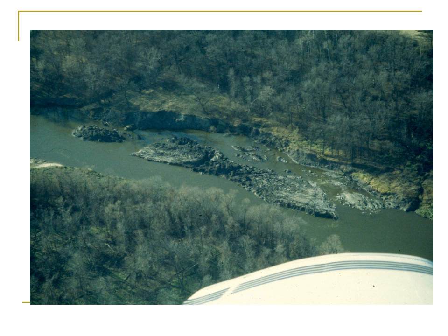This was slowly rotating along the slip surface, so they knew that the factor of safety was exactly equal to 1. And by using the Swedish circle method, they could estimate the strength of the soil and specify how to adjust the geometry of the slope so that a more stable soil configuration was achieved.